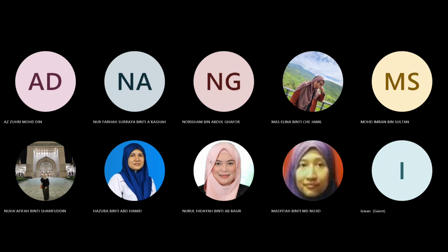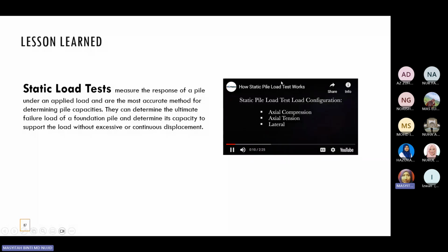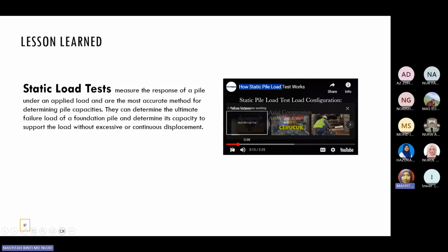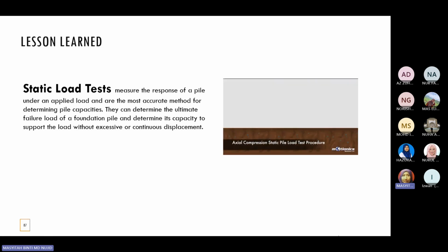Load test may be carried out in the following 3 load configurations: axial compression, axial tension, and lateral. Here, the procedure of a static pile load test with axial compression loading is explained.